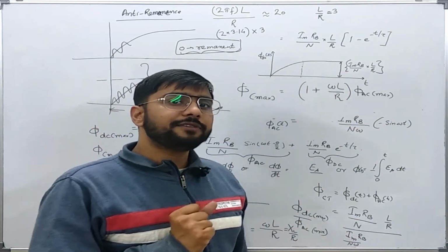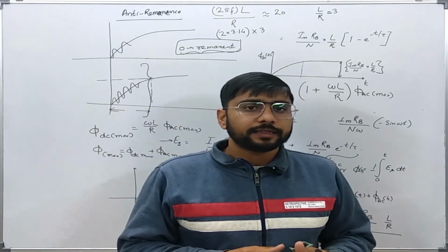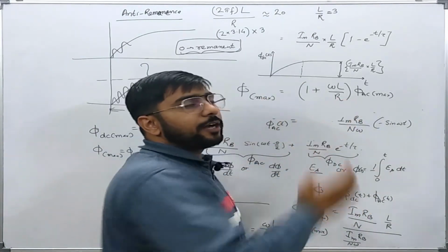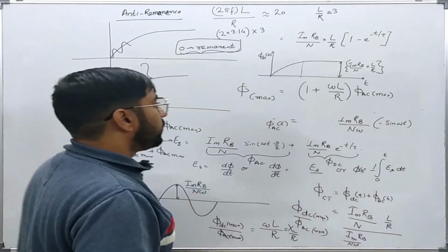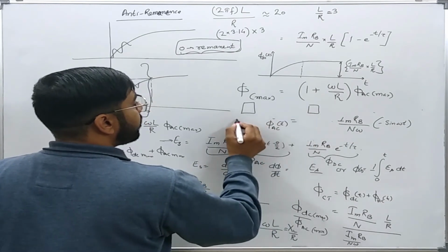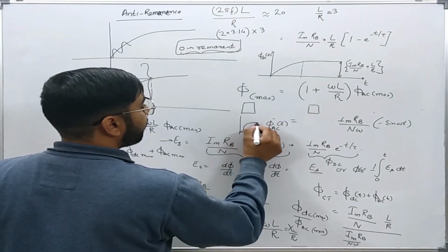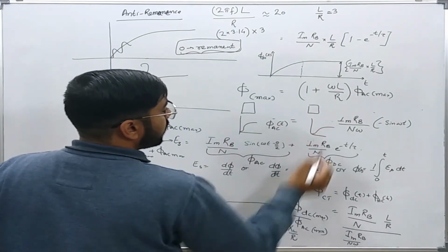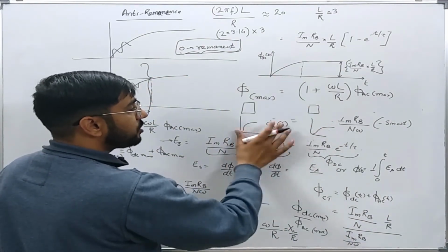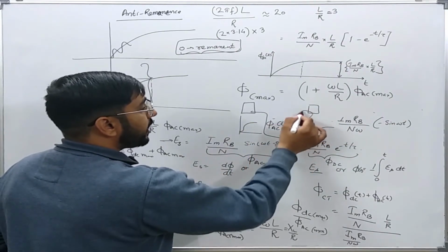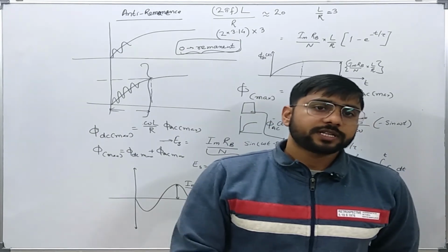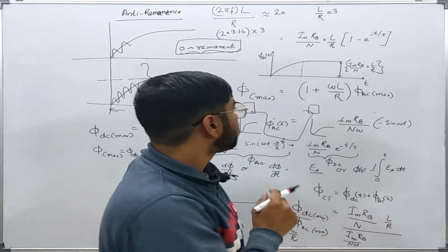However, whenever we are dealing with differential protection, there will be different CTs on one side and the other side of the protected equipment. The primary side CT and the secondary side CT may have different excitation curves, with small differences. Because of saturation occurring at different times in these two CTs, there can be a spillover current which can be detected by the differential relay, causing it to trip falsely during the transient.